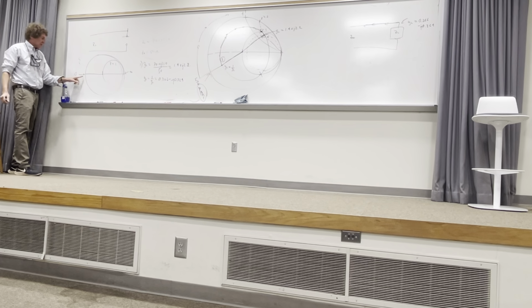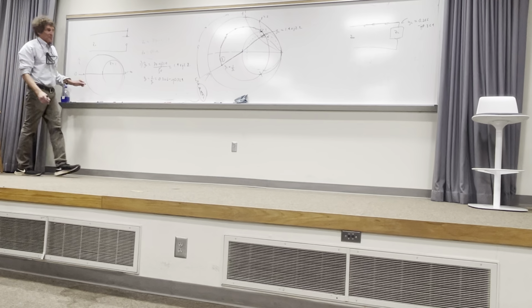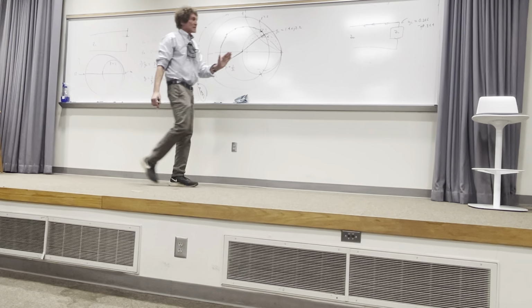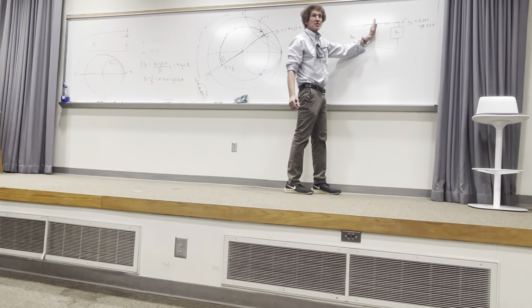But right now I'm talking about the value of the impedance. It's j0. Do y'all see this? It's right on the rim. There's no real component. Now they don't want the length that minimizes this, right? They want the stub value that minimizes the through line. Y'all hear me on this? So what they're talking about is they want the distance from the load to the attachment point to be the minimal distance.